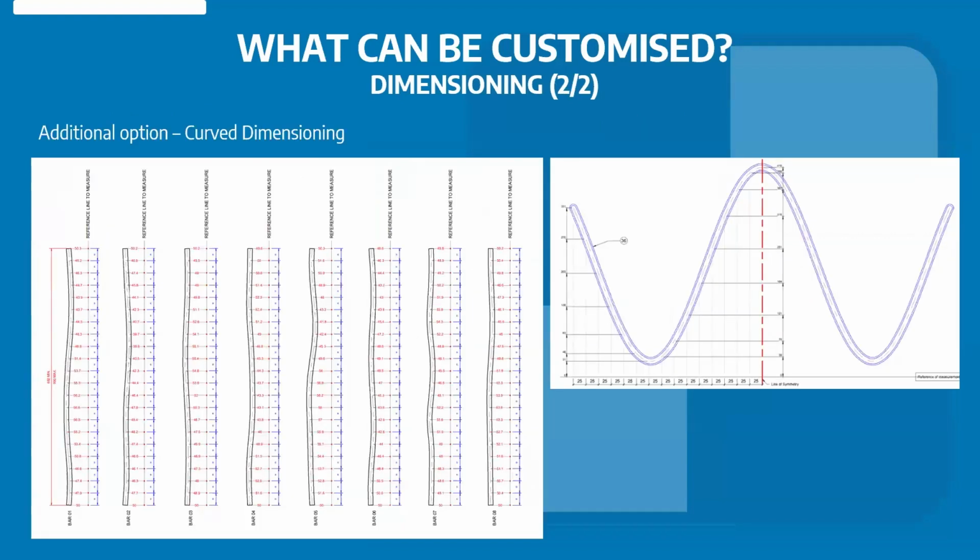All right, next slide. Here, this is an interesting thing to talk about. If your structure or your member is anyhow curved, then you can do a bit of a trick to do the dimensioning so that people who are in manufacturing or in construction can locate the position. Usually in the center of this slide, as you can see in this image, we use the ordinate dimension method.